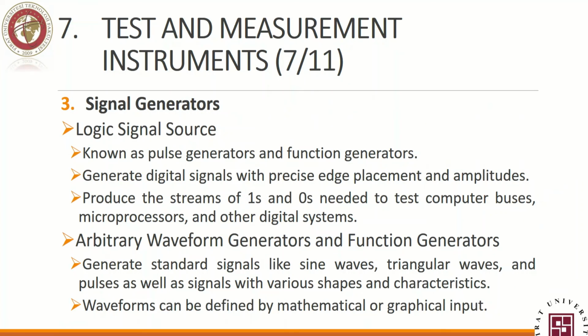A signal generator, of course we need to have a signal generator. Why? For any design, in order for you to check if it is working or not, you need to feed it with an input. Where do we get this input from? We need a signal generator. We need to have an input source. The input source could be a logic signal source, a series of ones and zeros, depending on what kind of stream you want. It could be a counter, it could be anything.